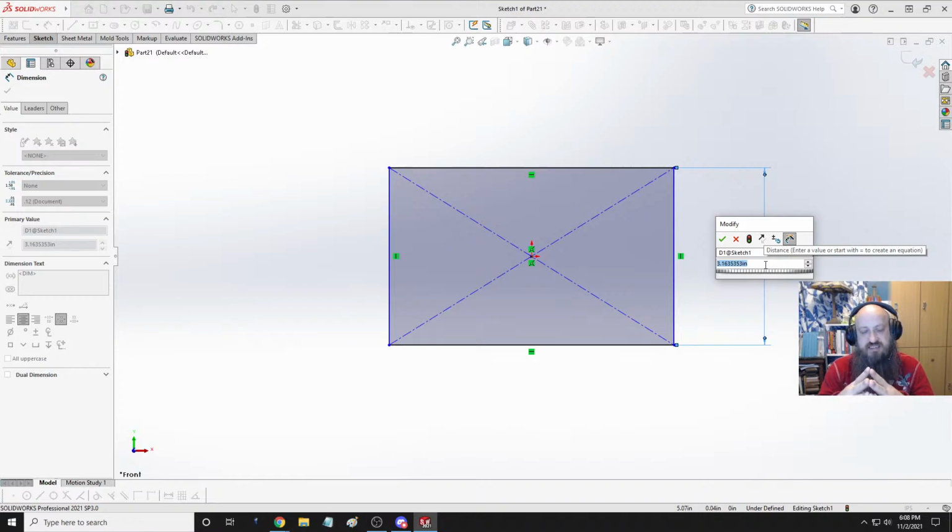there's a couple different techniques that are used in the industry. Basically, if you guys are familiar with wind turbines or even airplanes, the airfoil design is basically like a teardrop shape. So what they do is air coming in, or pressure or steam, because that's kind of what I'm basing this model off of. Steam comes in and flows over this airfoil, which creates a pressure differential and causes lift, which in turn causes it to spin, because they have a whole bunch of these.